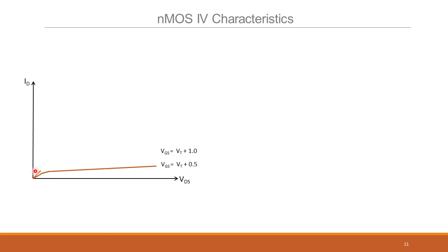The linear current itself increases, we saw that. Right? The VDS square then comes to reduce the rate of change of current, and then once it reaches VGS minus VT, now see this region, because VGS minus VT is larger, it moves out a little bit more. So VDS should be a little bit more larger. It's saturated here, this one saturates here, right? And then there is a VDS effect, which is the channel length modulation.